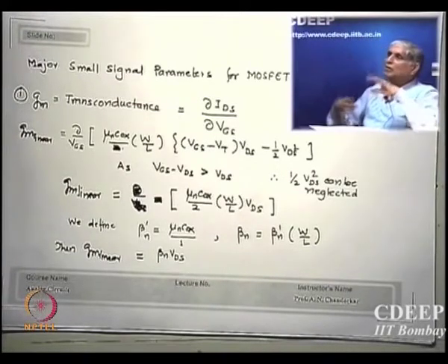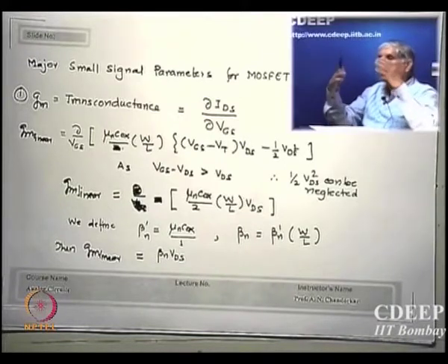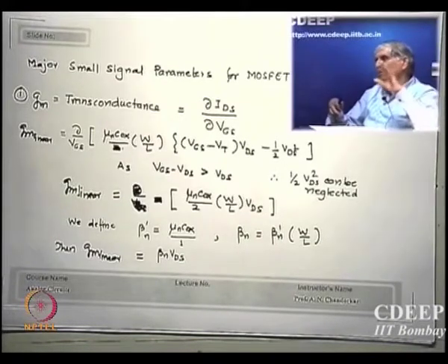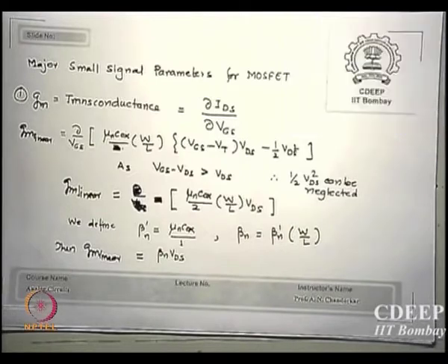There is a default parameter set for a given technology. Let us say a 5 micron process, they will give these values, it is called default. So initially when we are not giving our own data, we can assume whatever SPICE parameters are there and just solve the circuit for given input and output circuit parameters. Is that correct? So SPICE has an advantage: it can solve digital, it can solve AC, it can solve mixed signal, it can do all kinds of analysis very easily. Okay, and it is relatively fast, it has come from Berkeley and it is an industry standard.